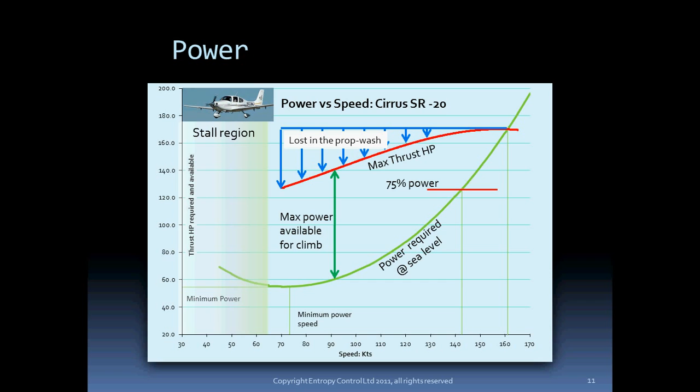A 30-degree bank turn will get us around in 24 seconds, but at a higher sink rate, 720 foot per minute. But if we have nerves of steel and can maintain that 73 knots in a balanced turn at about 30 degrees, we will be able to make it with enough time to straighten out and land properly. The big dangers are in not maintaining speed in the turn, or crossing the controls, or ruddering into the turn. Perhaps one wants to do the turn with feet flat on the floor. Whether or not this is a good idea is another thing. It's probably safer just to land straight ahead as you have been taught.